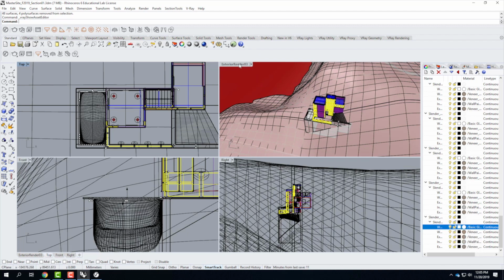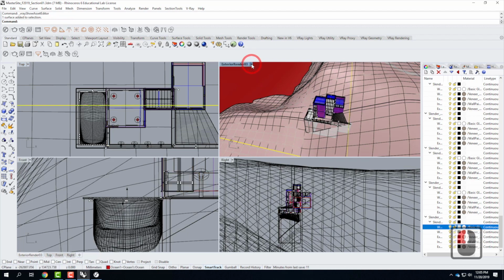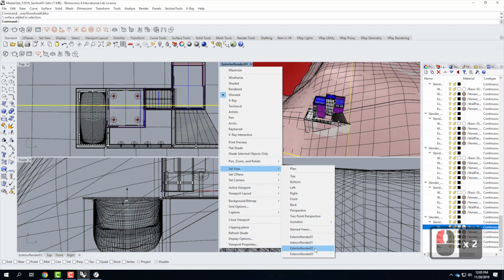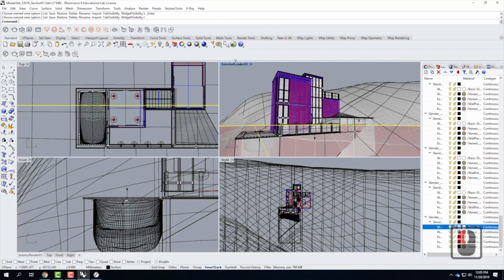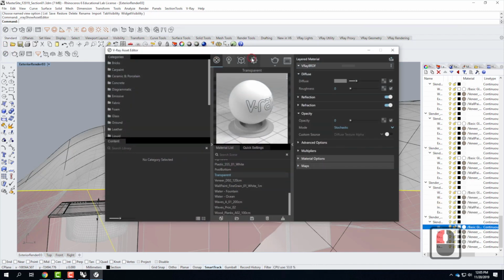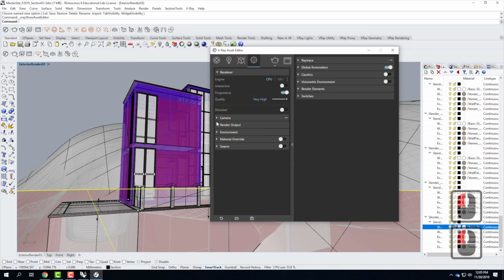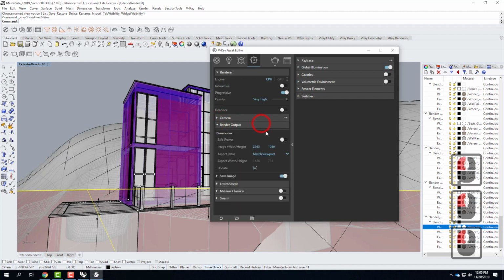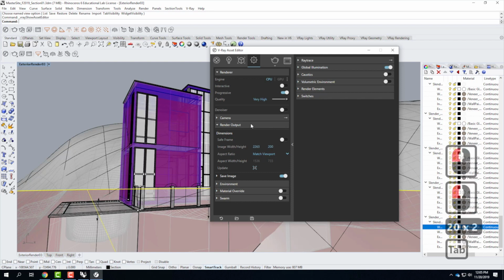Okay, so I have this set up. We'll go ahead and come back to where we can see my render. So I already have the exterior render 3 view right there. I can perform this same render, and you guys can get a sense for what it looks like. Let me go into my V-Ray options here. I'm going to change the size down for right now. Sorry, my render output. I can change that size down. We'll do it at maybe 200. There we go, so it's nice and small, and then we can do a test render. So I'll click on the render button.